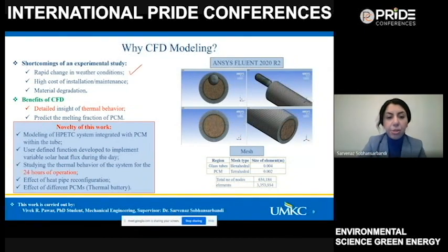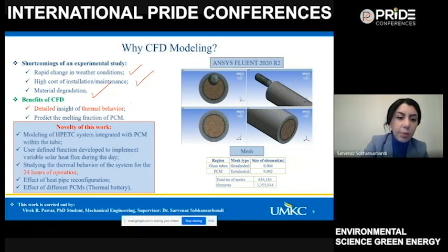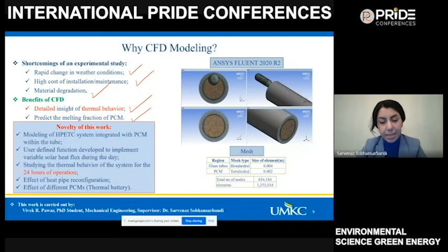Based off the rapid change in the weather conditions, as well as the high cost of the installation and maintenance, and the material degradation, for sure talking about the PCM, all of these help us to get a better insight into how the system performs through the CFD modeling. So the CFD analysis will give us detailed insight into the thermal behavior, how all of these parts move together within the system, and it also predicts the melting fraction of the PCM.